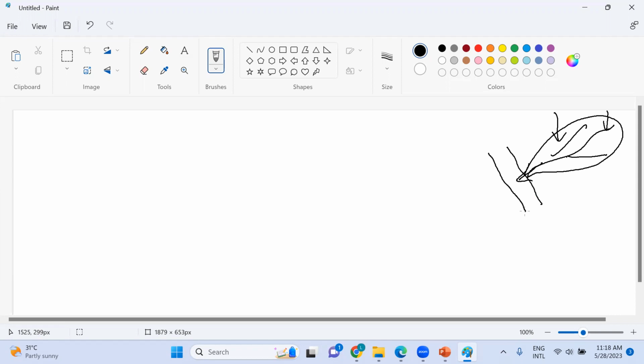Now, when you are designing it, you use the concept of the return period. Suppose that, have you studied the rational equation? I need you to answer yes or no. Yes, very good. You have learned it, right? So there, the peak flow is equal to CIA.